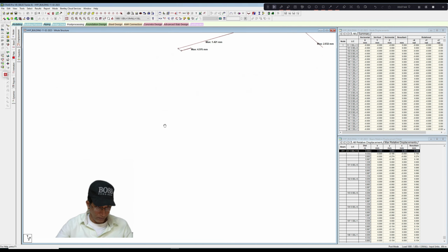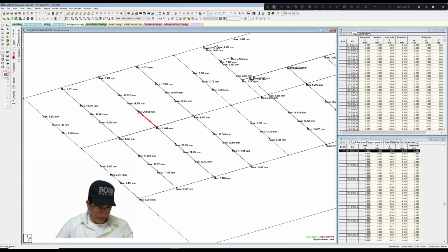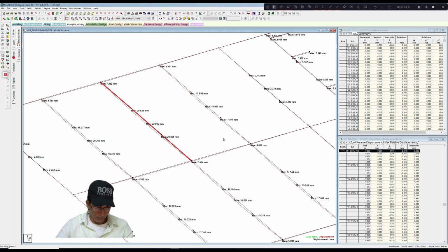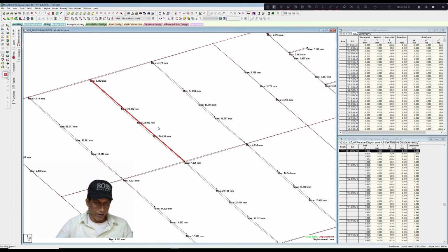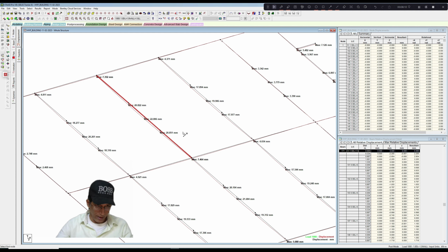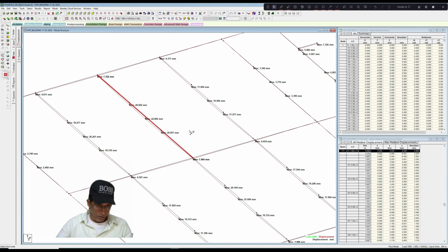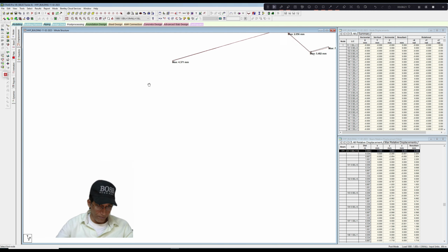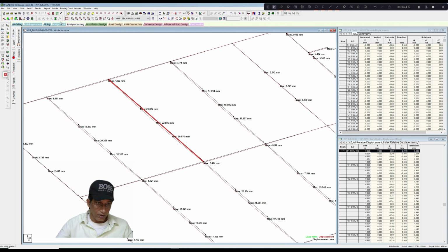Now see, the maximum deflection is here in this member, 22.806, and the length of this member is 4 meter. If we again draw this, take this line, the 4 meter display will be gone. So now if you see, for this joist, the deflection at end is,